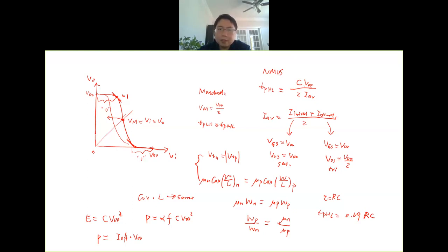So then here the average current assumes that the output changes from 100% to 50%. So you have the CVDD divided by 2, and this is essentially the charge you take out from the output capacitor. Then divided by the current, it gives you the time. So the average current is the initial point plus the final point divided by 2.